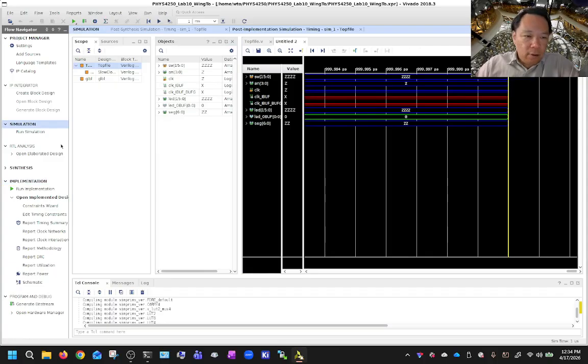And remember that in order for you to see these diagrams, you have to set this clock to something, because right now by default it gives you nothing because it doesn't know what your clock is. Once you set that up, you can have it go up and down, and you can see how your signal goes up and down and what delays are there in these clocks.